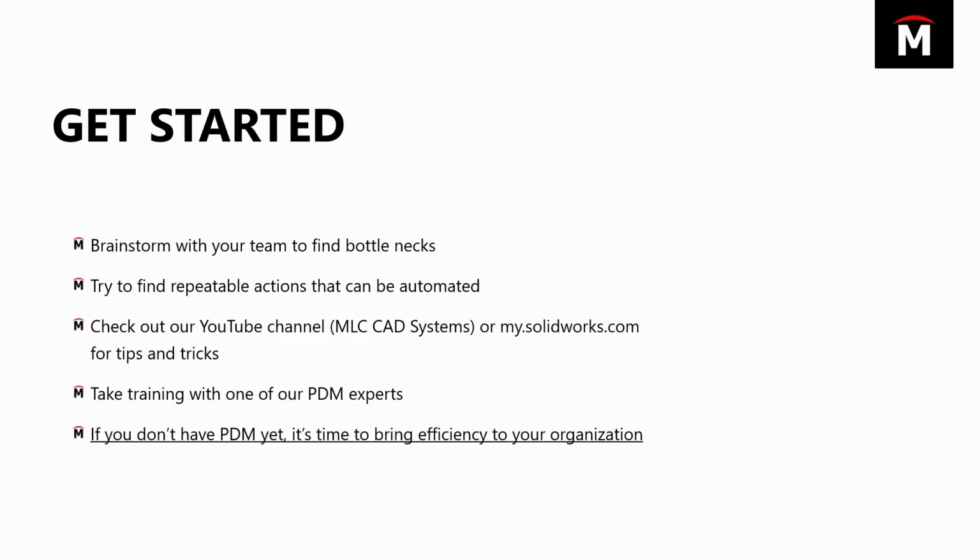The next thing I would do is try to find repeatable actions that can be automated. Look at your PDM workflow and say, every time we move from this state to this state, here's what needs to happen. Once you've identified those things, can they be automated, or how can they be automated? Can we use transitions? Can we use something like DRIVEWORKS or some other automation tools to get this done through that transition, to keep us from having to manually execute that task? So try to identify those repeatable actions that can be automated, whether they're in the middle of your design process or at the beginning, where you can utilize something like templates.